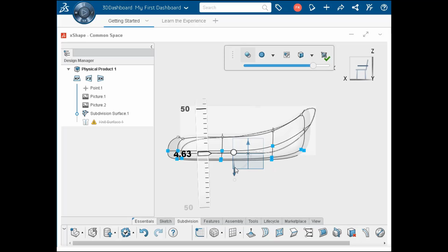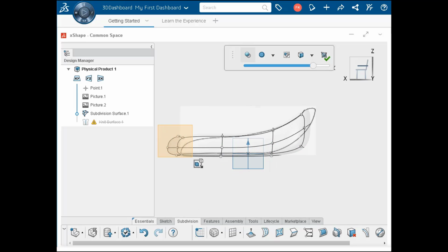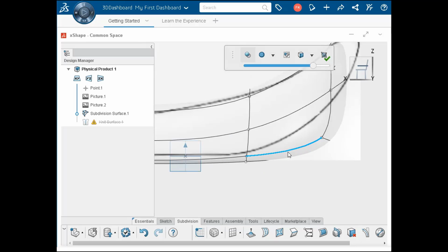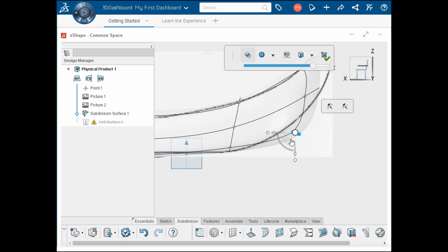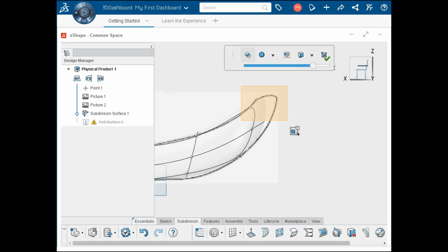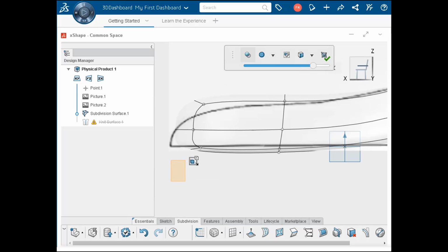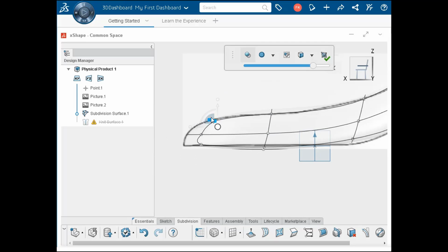As you might expect, there are quite a few pushes and pulls needed to get to the shape we want. Let's speed up the picks here to save some time. An alternative to box selection of vertices is to use the selection options to filter types such as vertices, edges, faces, edge rings, edge loops, and face loops. Any entities is the default setting.